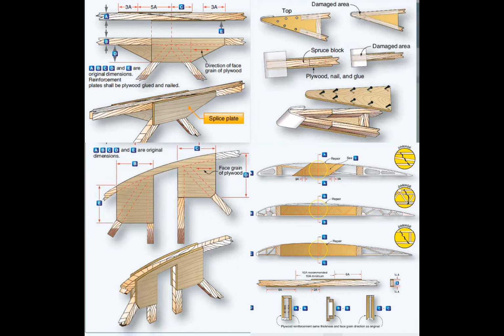What would be the greatest number of splices placed into one spar? 2. What is the largest hole diameter that can be repaired in a plywood wing skin when using a fabric patch? 1 inch.